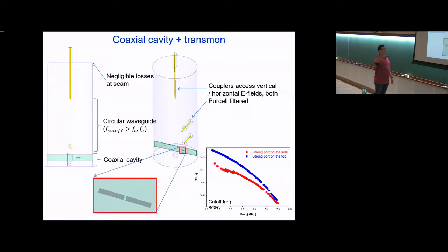And then basically we just put some microwave ports in here. And there's a certain subtlety that you should put the ports and structure the cavity in the right way so that you really make it very easy for light to get out at the cavity frequency and very hard for the light, the photon trapped inside this nonlinear qubit here, to escape.